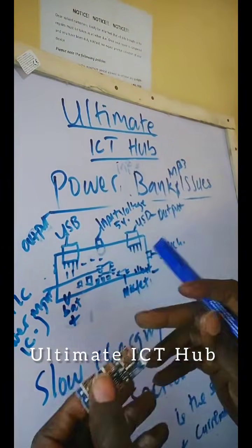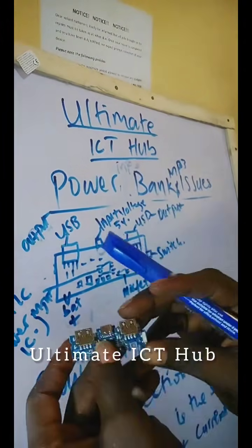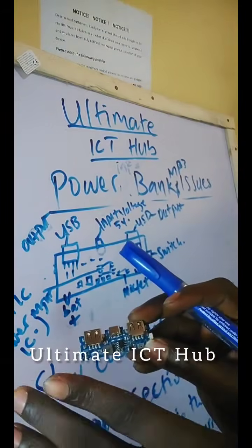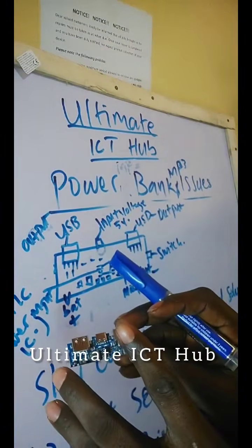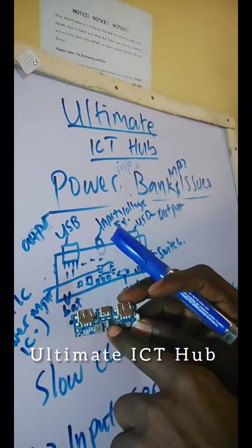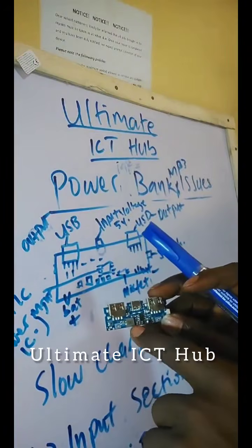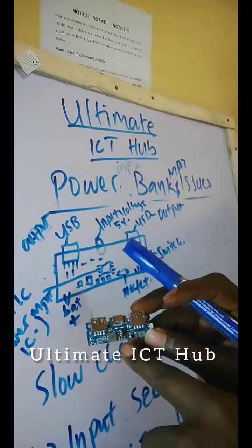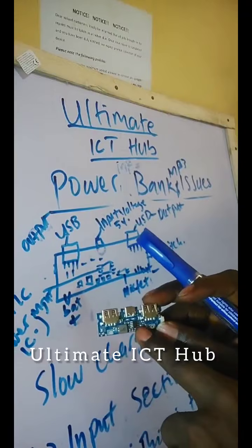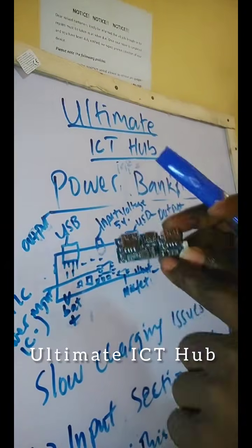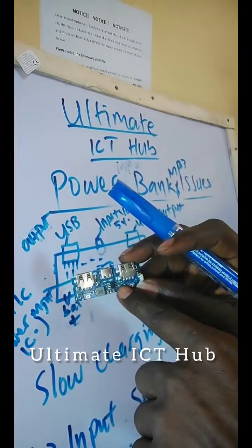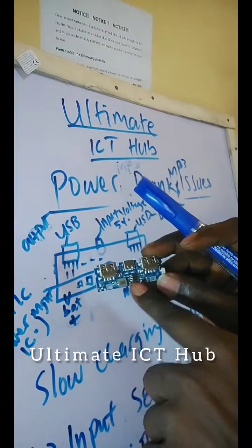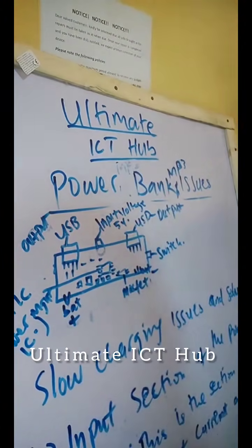What the power IC does is to supply current into the module or the PCB. You understand? That's just it. And to regulate it. So around the power IC, like I've always said, you must have capacitors around it. This has 1, 2, 3 capacitors, and it has 1, 2, 3. Okay, we have another, smaller capacitor. These things are called ceramic capacitors.